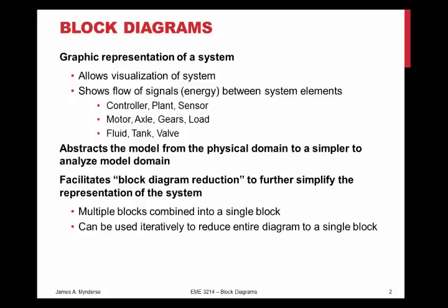And then the second step is, once we've got all these equations into picture form, we'll do algebra on the picture instead of the equations, and that's the reduction part. Reduction just means we're going to take two blocks and combine them into one block. If we keep repeating that process, instead of a whole loop with a bunch of different blocks, or maybe multiple loops, like the example that I'll show you in the next video, we're going to end up with just one block that corresponds to one input and one output. And that will describe the entire system.